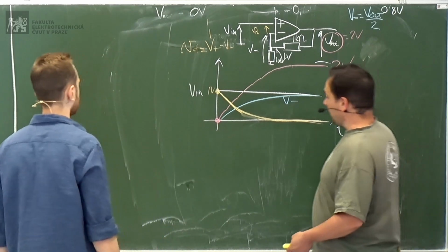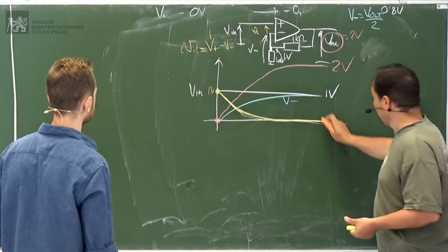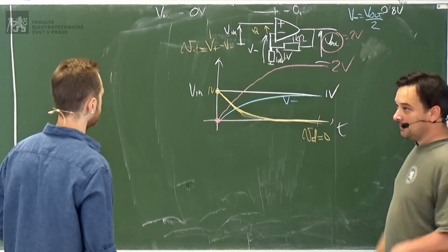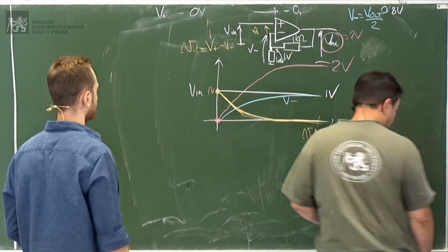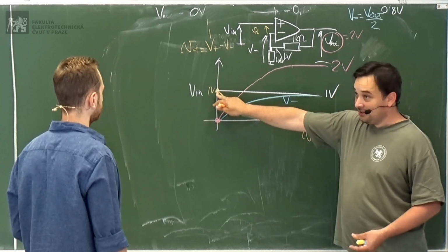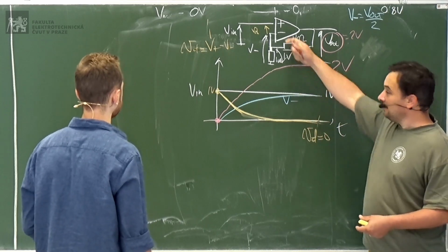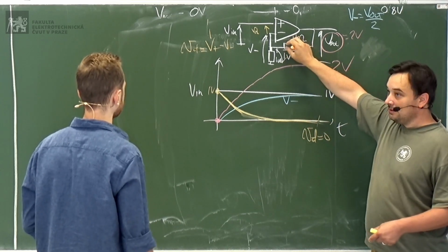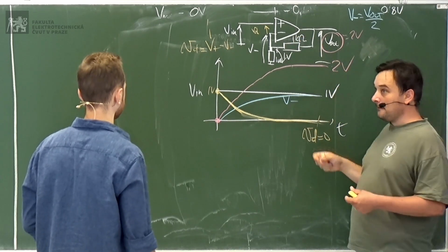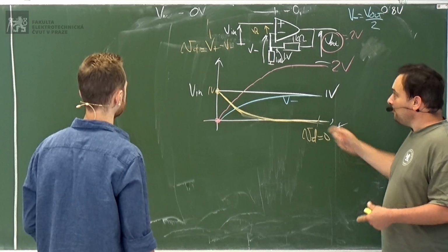This is how the operational amplifier works. If you are here, VD is 0, and you're happy about that. But in order to get to 0, it will start from a point where it's not 0, and then it gives the indication to the amp how to change V out in order to go back to 0. This is important because it tells you that it's not always 0.